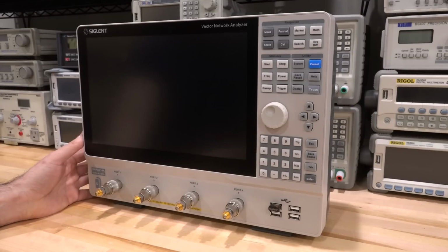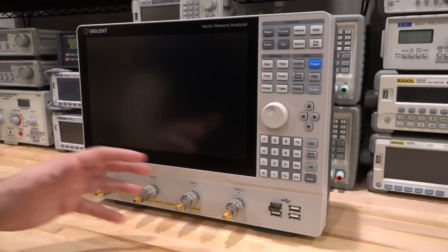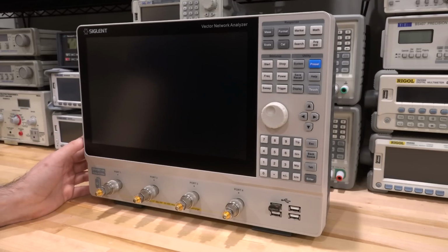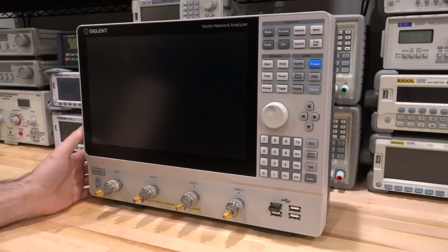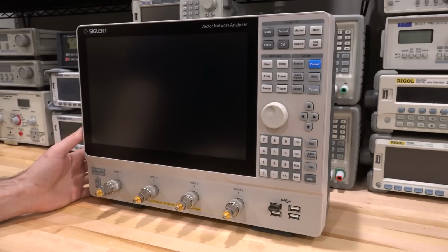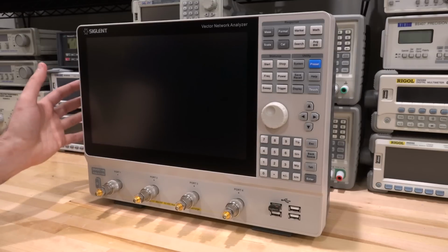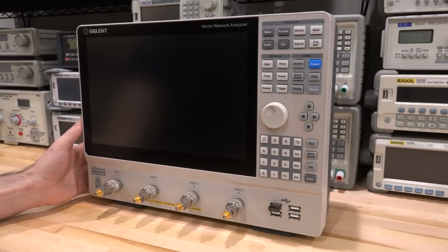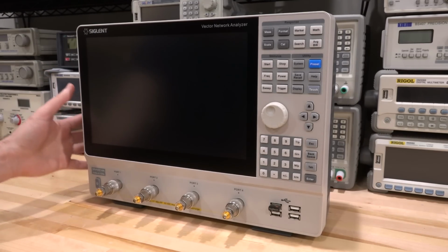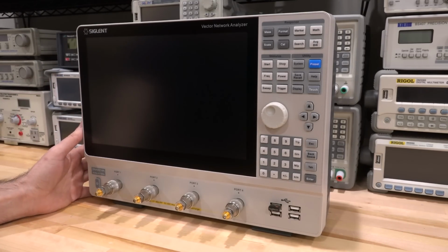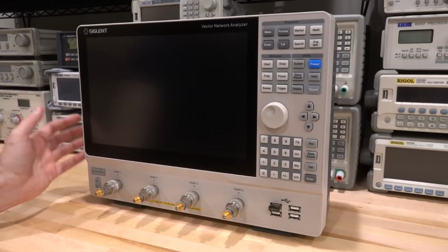In fact, you can do nonlinear measurements, mixer measurements, because you have enough synthesizers to down-convert across different frequencies. And if you have pulse generation and detection capability, you can do TDR measurements as well and create eye diagrams of various channels. So the capability of this instrument now depends a lot on software development. And Siglent has indeed continued to develop a variety of software for it, and I want to take a look at some of those interesting applications.